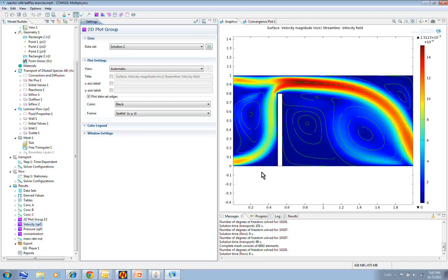What I haven't done is put a restriction on the pressure that is required to move this flow rate through the reactor. Because there's no constraint on the pressure, I guess limit yourself to, say, no more than 4 baffles. Give it a try, and see what kind of mass rate you can come up with.